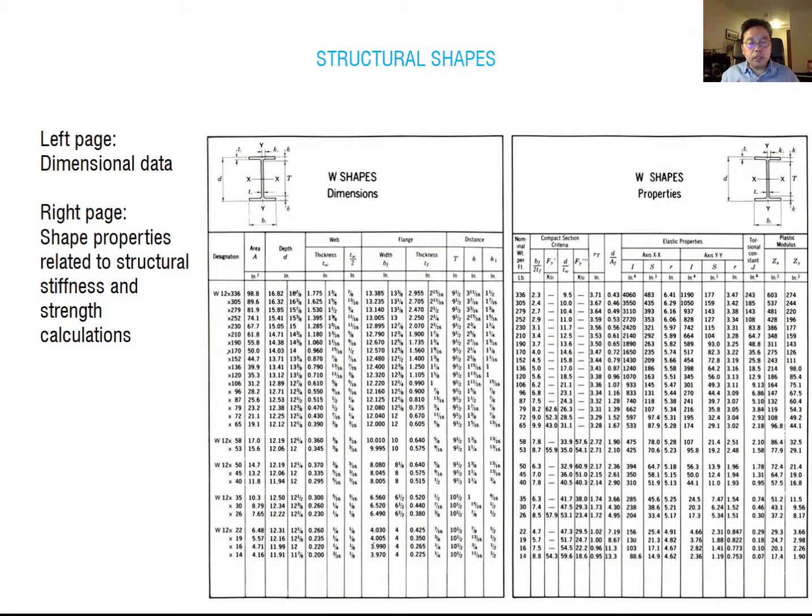Wow, it's lots of different information here. But you don't need to worry about the weight and any other thing. You only consider the height and width. Okay? Because height is important to designing your section because it impacts the ceiling height. So that's why you're simply comparing the height, width and length. I think this is the only effect on your design. It doesn't matter much about the weight, right? So when the structure engineer provides a nominal number, which is a W20 by 40 whatever, you can simply find this number in this book and find out the actual dimension and adapt it to your design.